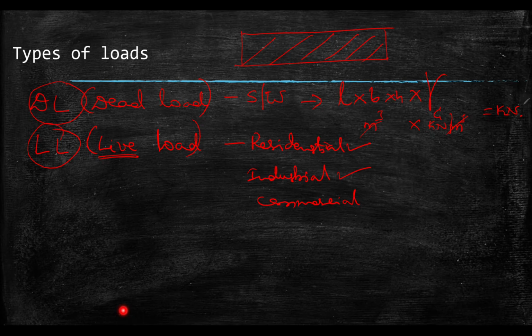So these are the two things you need to consider, even if you are taking even a single sway, that is a single story portal frame also. So you need to take this. You will be having the dead load plus live load. Any structure should be designed for dead load plus live load.